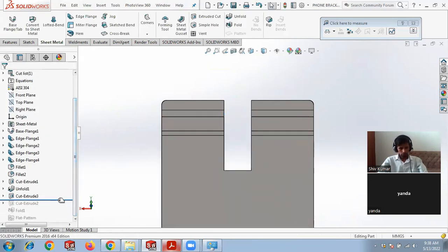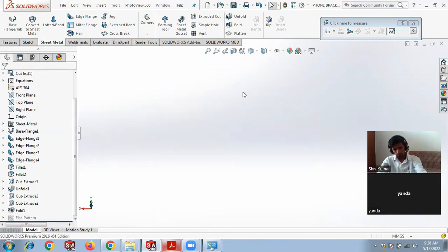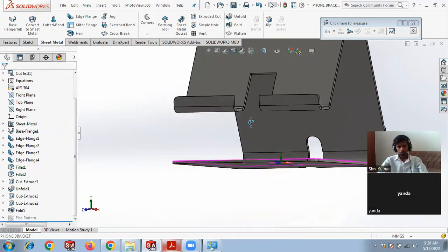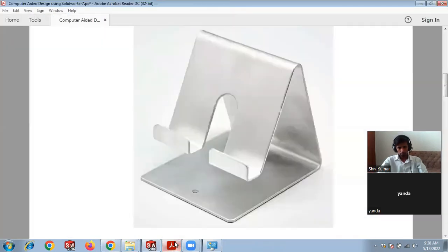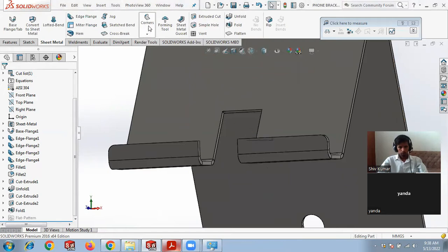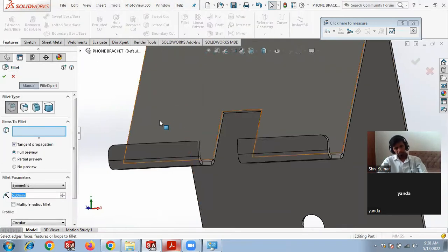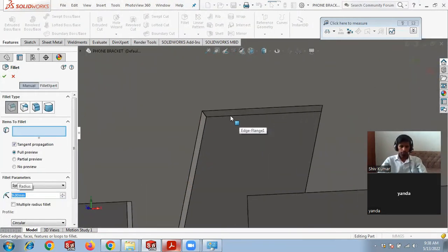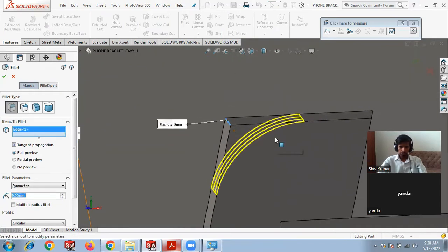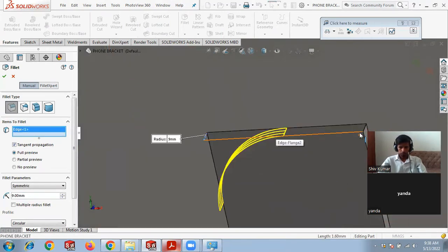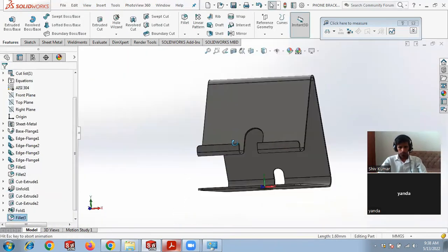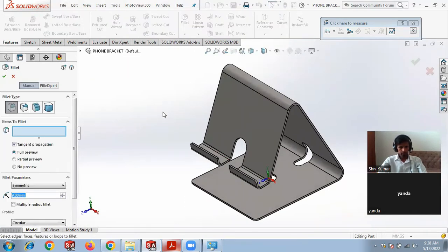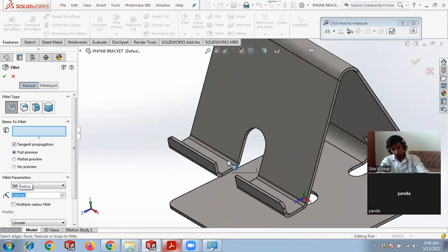Again, I just used the existing fold, unfold, fold, unfold. Getting my point? Okay. So similar way, I can apply fillet. I'm taking radius 9 mm, because the length is 18 mm. So I'm taking radius, and again selecting fillet. It is to be 3 mm, I think.